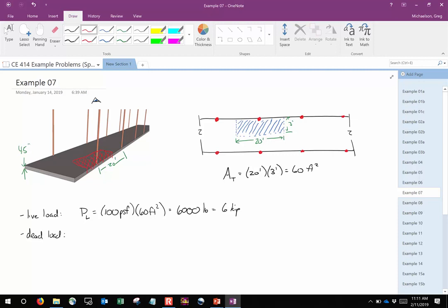There you go. 20 times 3 times 4.5 inches, right? But you've got to be cognizant. Now we're going to multiply that times the unit weight of concrete. What do you think is a reasonable value for that? 150 what? Remember, you write out those units.